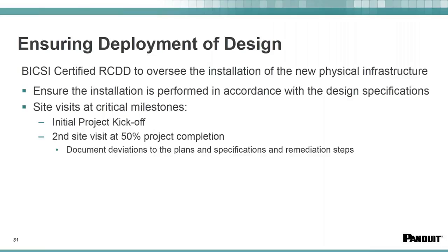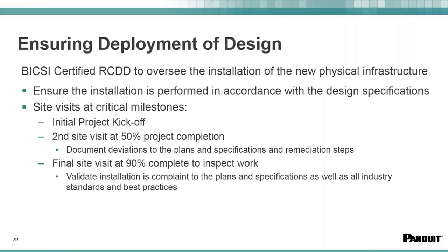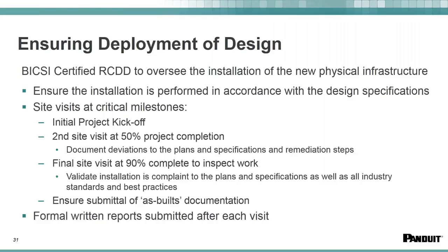We'll develop a punch list and remediation steps that need to be achieved at that 50% level, and then we'll come back again at the 90% level to make sure that everything has been installed per the specifications, acting as an owner's rep to make sure that all the standards have been achieved, and that all the as-built documentation, etc., has been provided.